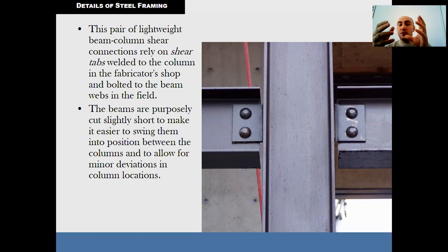The additional member is also called the child member. The connection can have either an L-shaped bracket on one side or two brackets on both sides. Having double angle connections increases the rigidity of the connection. It's stronger in resisting the shear forces.